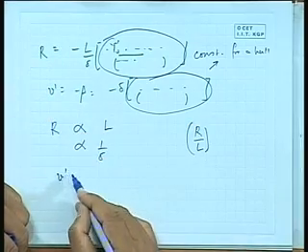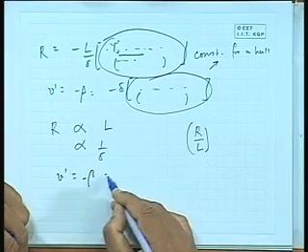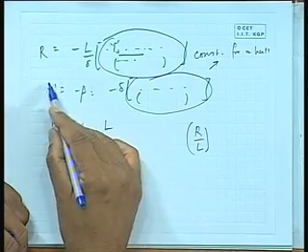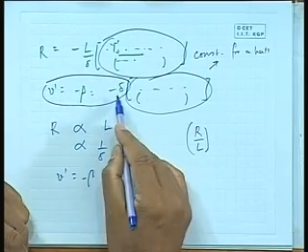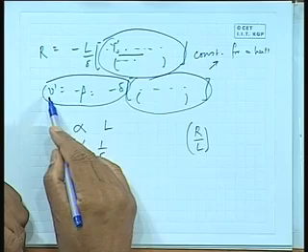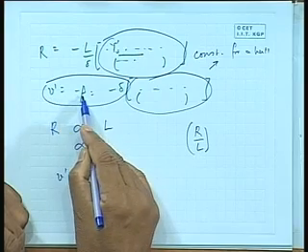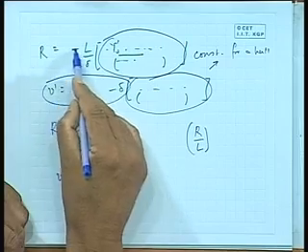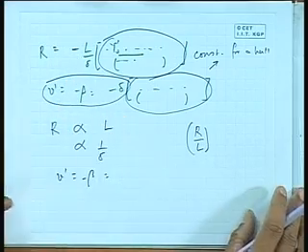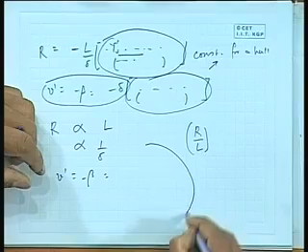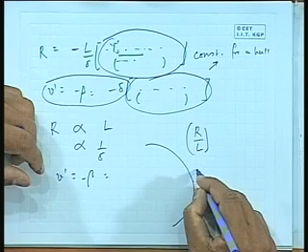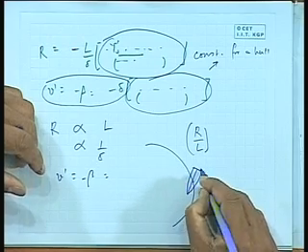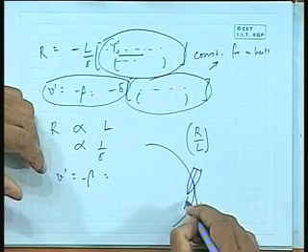V dash equal to minus beta, if you see this part, v dash and delta are related. More delta, more v dash means more drift angle. Without proving, from this sign, minus and plus, one can tell you that if you give a port rudder, the ship is going to turn to the other side. This basically means that if the ship is turning fast, it is going to have a very large drift angle, this beta angle.